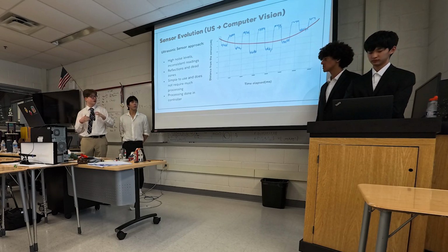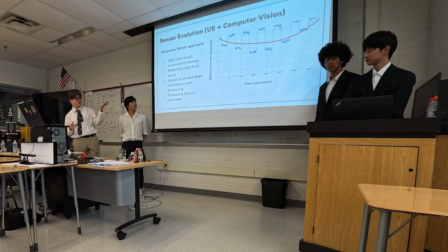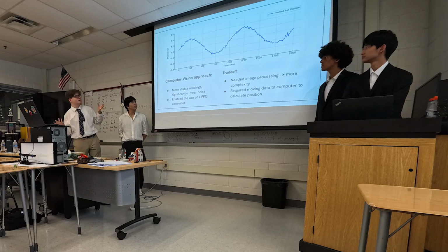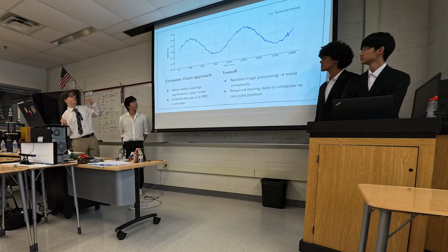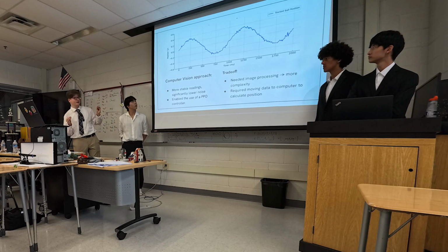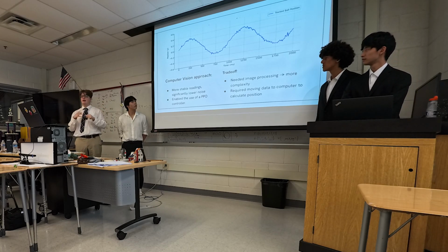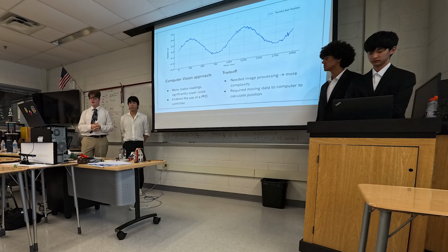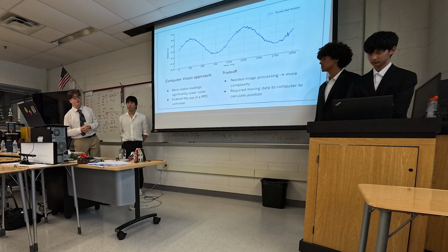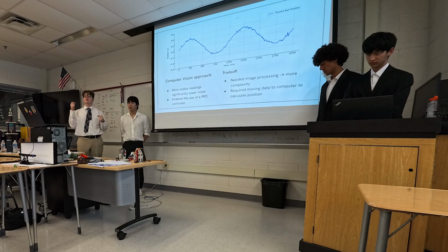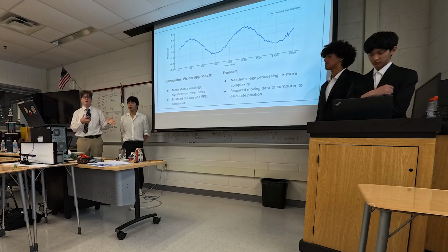So we decided to switch over to a computer vision model. Now here is a more zoomed in picture because I thought it would be better to see, and we can see here that the sine wave is very tight in terms of its error. This worked out a lot better in terms of precision, but there were some trade-offs, mainly the time to process and calculate the position of the ball. Before, when I used the ultrasonic sensor, it was very simple: I could just get the ultrasonic sensor data, and that was my position.